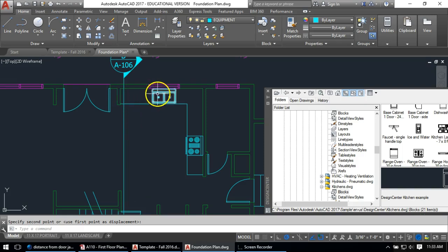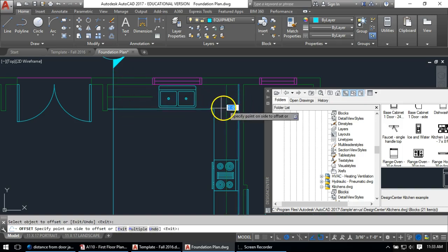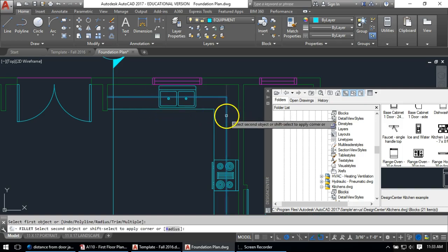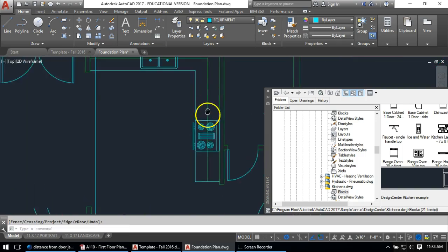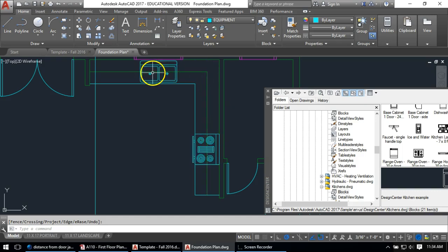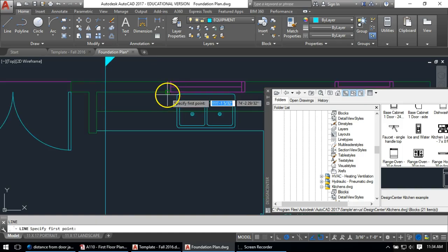We see there are dotted lines here, here, here, and here. Those are the upper cabinets. They are typically 1 foot out from the wall, so I'm going to start by offsetting 1 foot here, and fill it together here to here. This will be aligned with the cabinet, so I'll trim it along there. This probably turns into a hood, so the line can continue across, but we usually don't put cabinets above sinks or in front of windows. So I'm going to draw a line down from the edge of the windows and trim the upper cabinets in between.